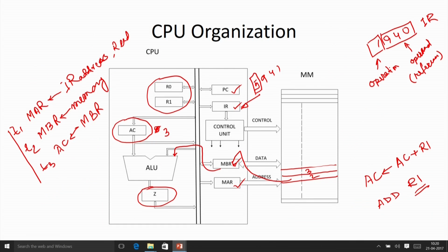This 5 indicates what operation we are going to perform. We add the contents of the accumulator to the value brought from memory, get the result in temporary register Z, and from this temporary register we transfer it to the accumulator. So, now the accumulator value becomes 5.